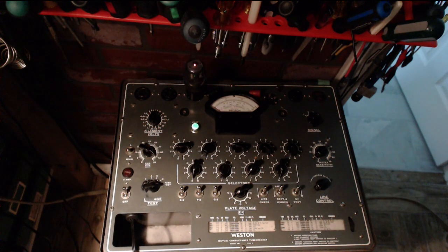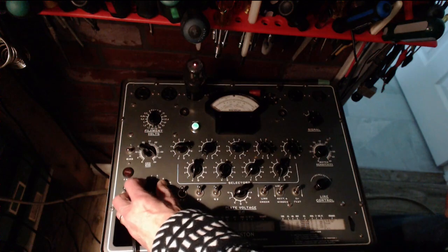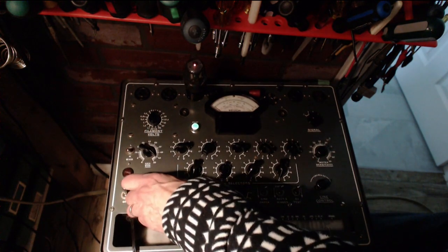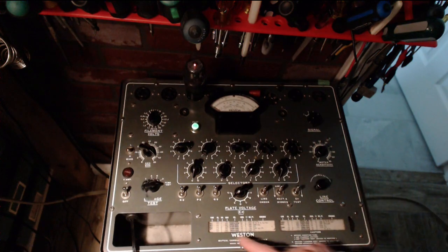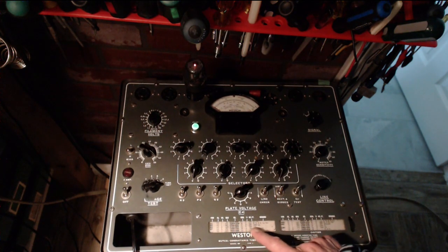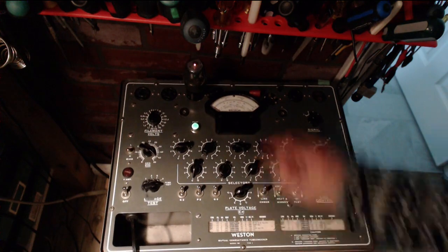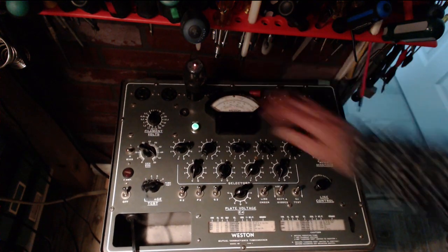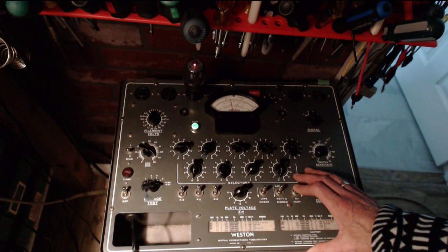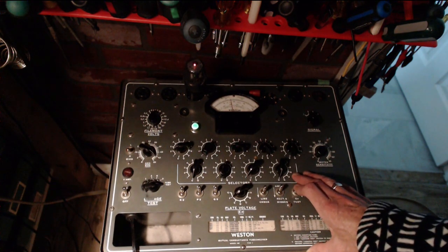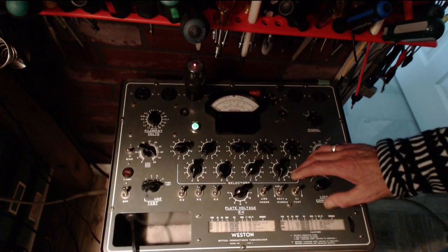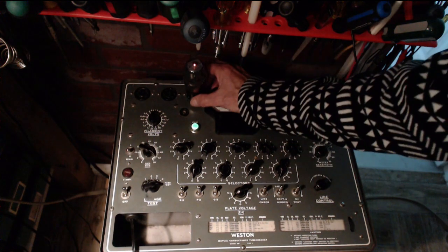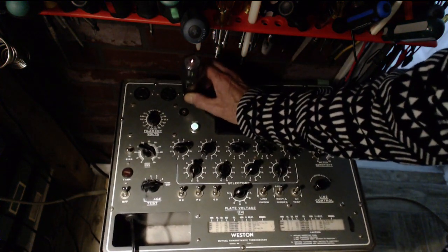Okay, good. Now, this guy. Okay, that's normal. GM on this tube: to get the actual GM though, we actually have to multiply the reading by 2. It has to come up above 830 on the scale. There we go. Well, that's really good. No doubt about it. That is a good one. Oh, good. Yeah, good. Don't push your leg. Good one here. So the good one is going to go right back in the radio.